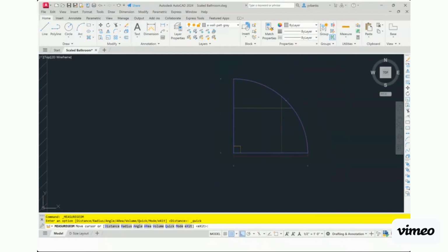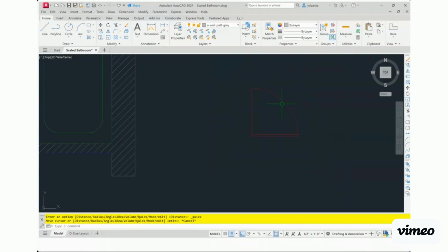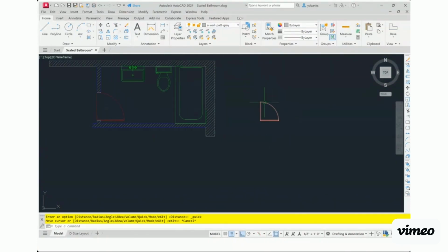Okay. So, as you can see, when we scale, either to enlarge or decrease items, whatever the object that we choose to scale will automatically adapt to what we want. Once we have selected it, choose the distance and type in the actual measurement, or choose a placement and type in the measurement where we want our object to be scaled to.